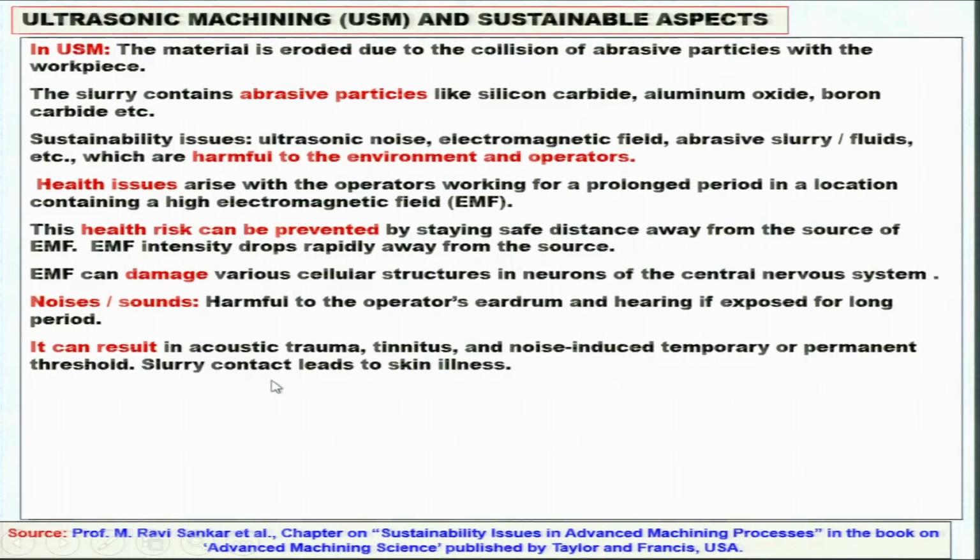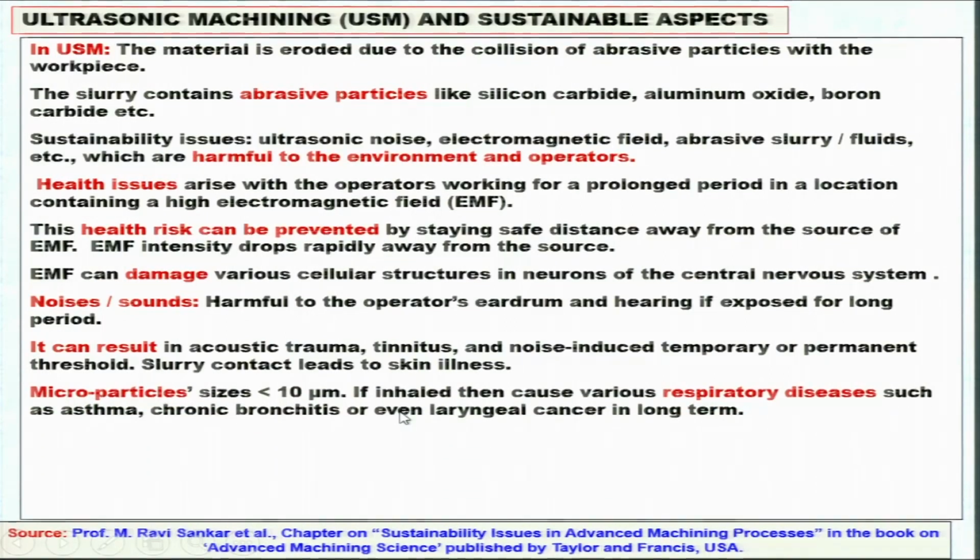Slurry contact leads to skin illness. The slurry of the ultrasonic machining should not be touched by the operator with bare hands, otherwise it will lead to skin illness. Microparticles of sizes less than 10 micron, if inhaled, cause serious respiratory diseases such as asthma, chronic bronchitis, or even laryngeal cancer in the long term.